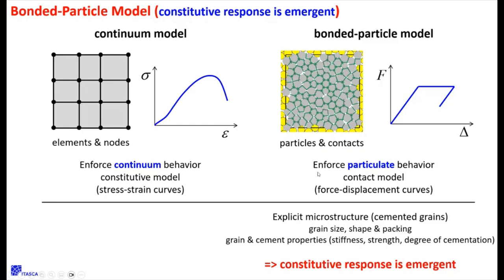And we can do this for a general shape. We just have a bunch of walls. We always have to enclose the PFC with a bunch of walls, and those walls will fit the shape of the removed elements. Then those walls are slaved so that they move just like this guy. So when this guy deforms, PFC gets loaded because the walls move. And as soon as the walls move, PFC naturally builds up forces, right? So that's coupling one way.